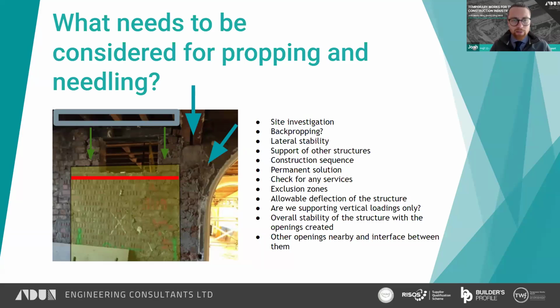So if we go through our list that I've put down the right-hand side, site investigation. So here we'd be interested in wall thickness, the layout of the structure, including floor spans and floor-to-ceiling heights, the floor construction, so we can work out how heavy that is and what it's made out of. That's really going to be important to determine what the loading is on our props, which leads us back to back propping. So if we've got the loading from our props, then what are the props going to be sitting on? Is it feasible to back prop below? The floor below may be occupied by a third party. So we need to know those kind of things.